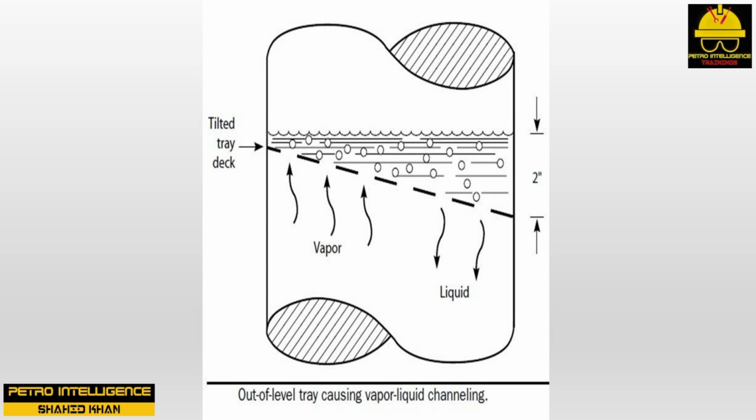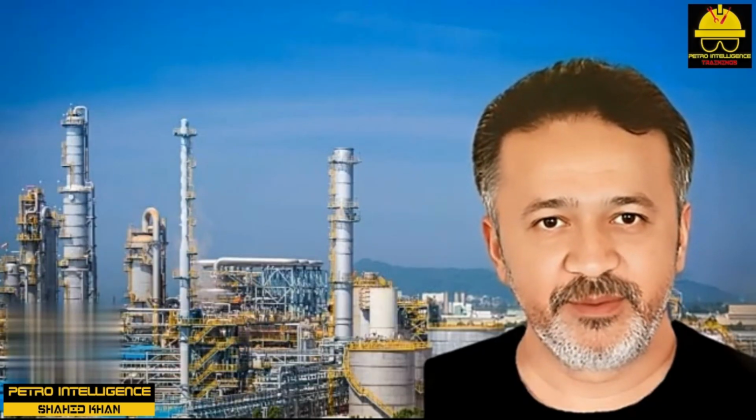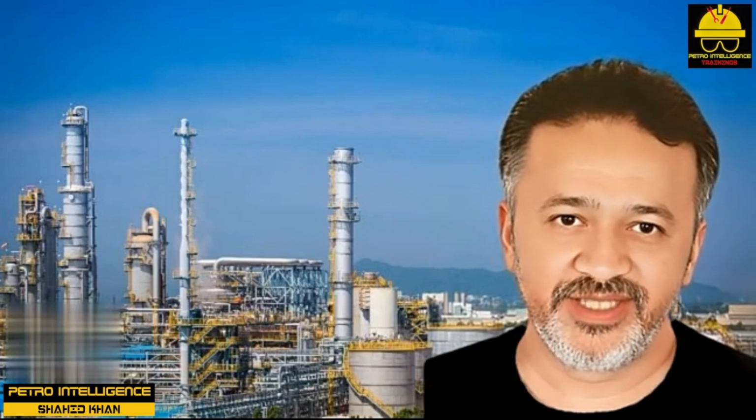Channeling is the primary reason for reduced distillation tray efficiency, because the vapor and liquid no longer come into good, intimate contact. The common reason for out-of-levelness of trays is sagging of the tray decks. Sags are caused by pressure surges and sloppy installation. Sometimes the tray support rings might not be installed level, or the tower itself might be out of plumb, meaning the tower itself may not be truly vertical.